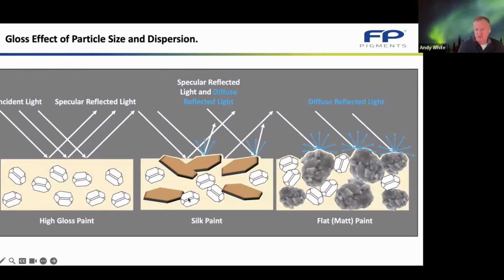As you go into semi-gloss paints and matte paints where you've got fillers, you're going to see that these differences, you cannot see them. Again, which is why in primers and matte paints, sulfate processed pigments tend to be able to be used alongside chloride and are therefore much cheaper to use than elsewhere.